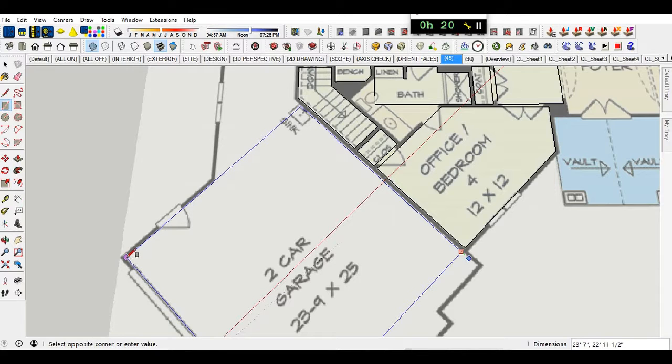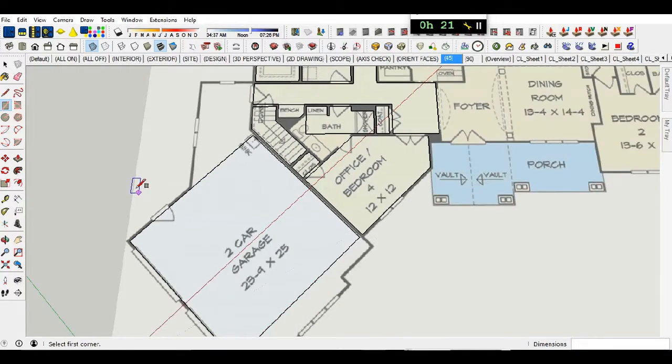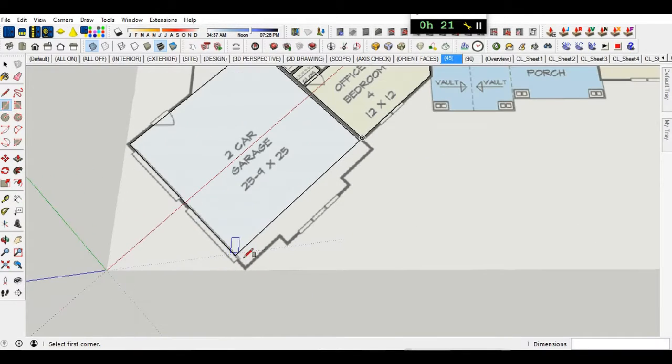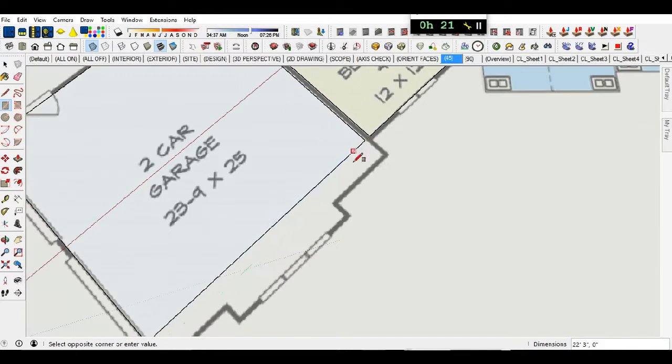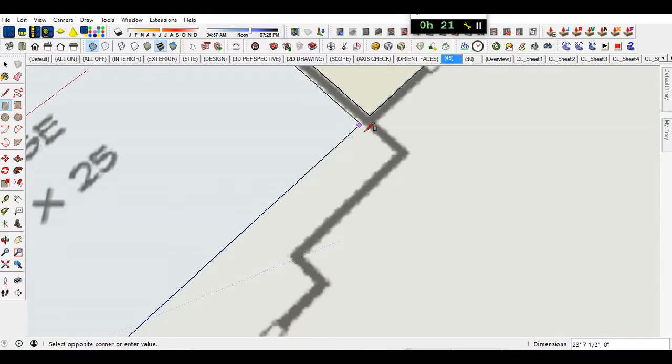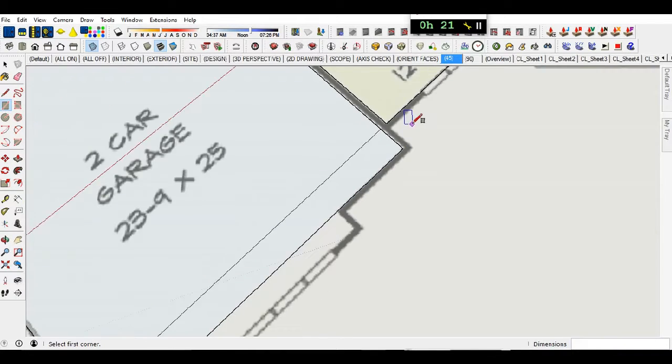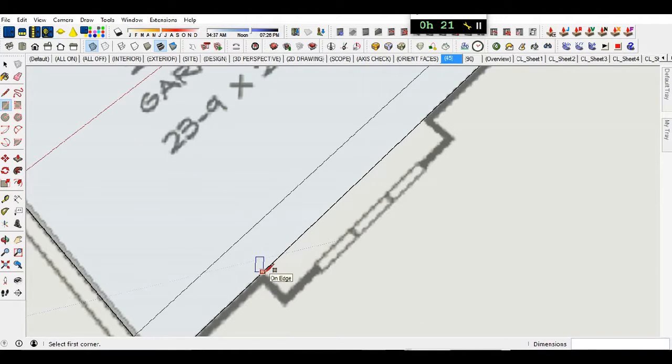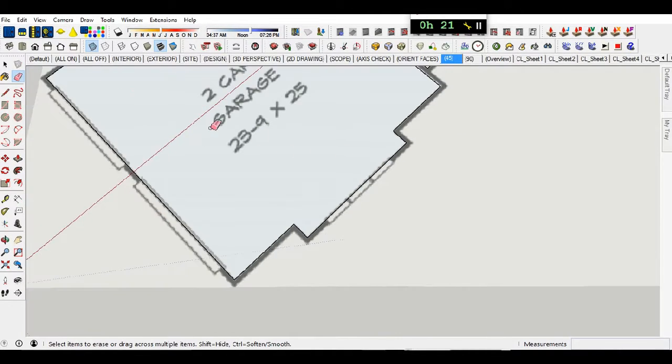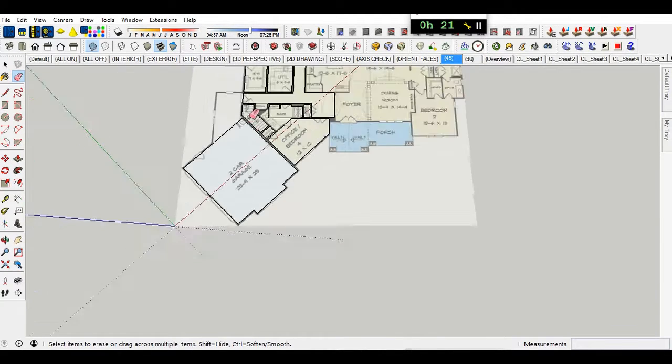And then switch back. Oh wait, let's go ahead and get the bathroom while we're on the 45. I will reference off of this bottom corner here in the red direction, holding shift in the corner, and then go ahead and drag up until these two sides line up where I want them, but make sure that I'm referencing on this line here.